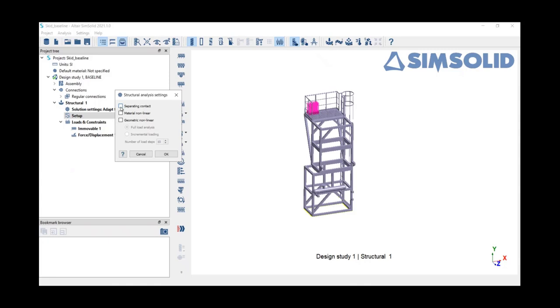You will notice that some of them you can't cross-pollinate with each other, and you will see that if you click OK, it will guide you through what's supported. So in this case, it'll say geometric nonlinear with separating contact not yet supported. Like I said, we're going to keep this as a linear static analysis.